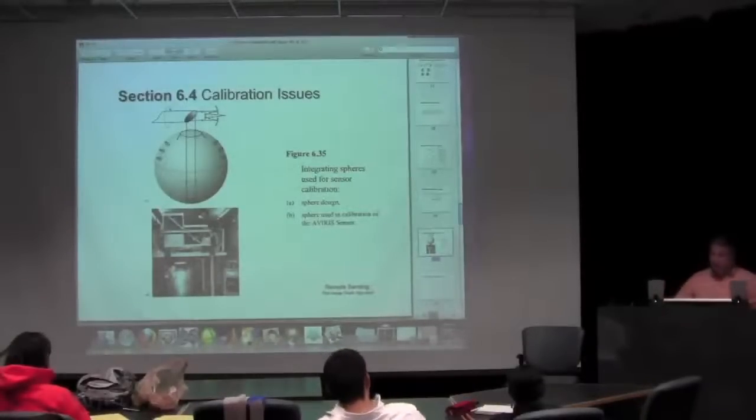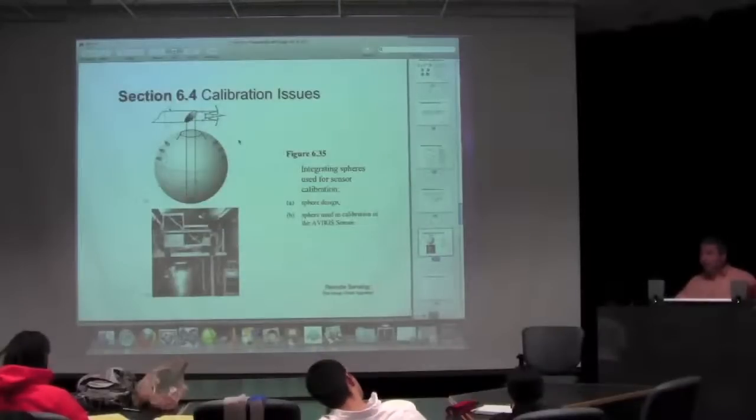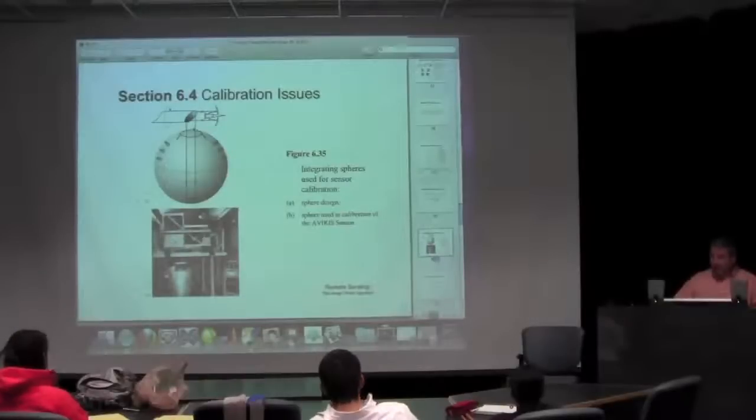So these bulbs need to be very tightly controlled with a uniform power supply, and you've got to set it to the very specific value that NIST said to get those radiances out. And if you do that, you can get a very controlled signal out here, a NIST calibration certified signal out of the sphere.